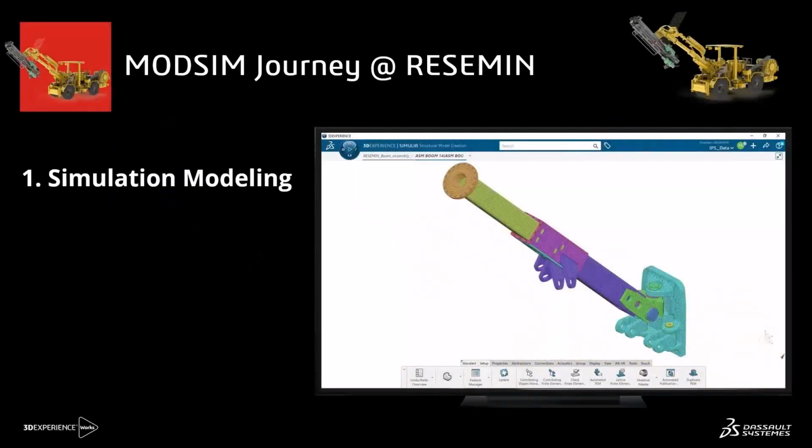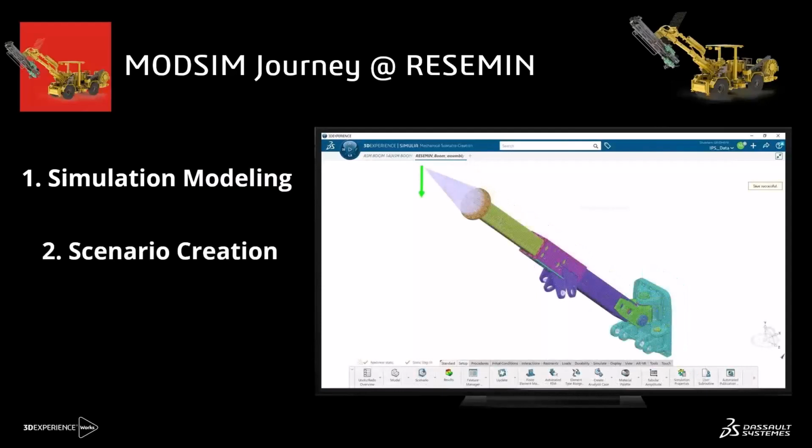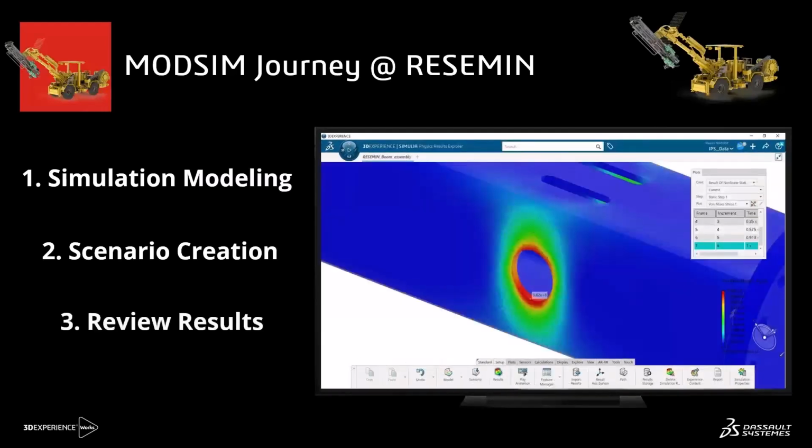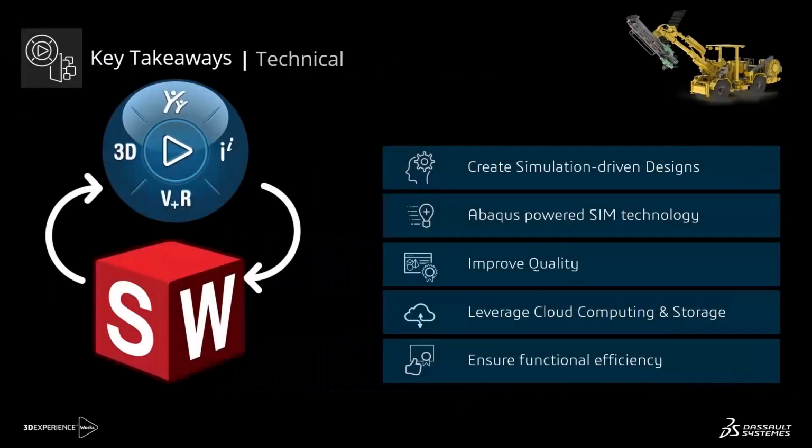The analyst is going to set things up with a finite element representation for materials, meshing, and different model connections that they want to use. Then they'll create a scenario that has the inputs of loading and fixtures, and finally review those results, whether we're going to leverage updates back and forth or just share those results with others on the team.